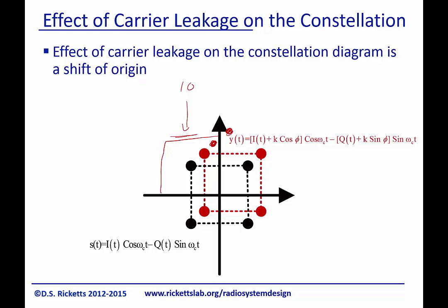Typically what will happen is we can actually shift these boxes. This is the received box so that it's centered around there. That's something we can do if we want to try to fix an offset that we know has happened. But if we don't know the offset's there, we'll be looking right around here for the signal, and if it's not there, we could have an incorrect reception or an error.